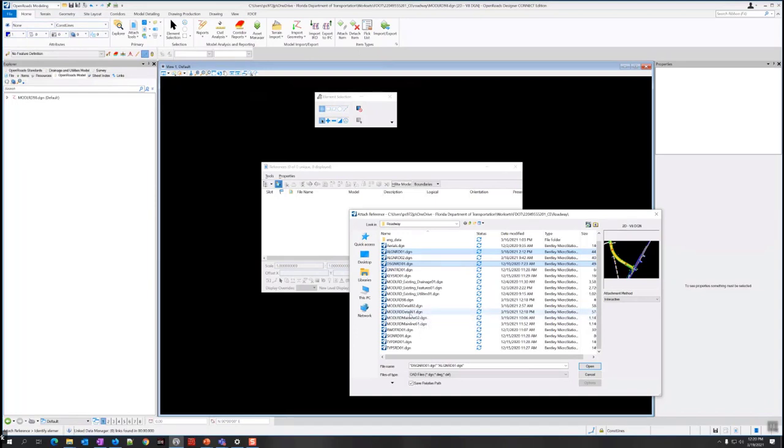If I were doing detail modeling in the same one as the mainline, it would give me a problem when I go to do earthwork, because either I have to detach it and lose all the connections there, or it's going to calculate it. Even if the display is turned off, it's going to calculate all the earthwork from the other road as well. So just something to keep in mind. I know earthwork's a chapter down the road, but I just want to make sure you're clear on that, because this is a little bit different than workflow.